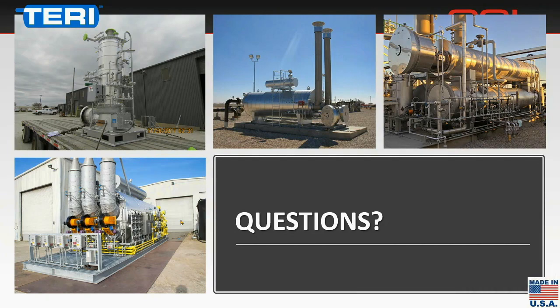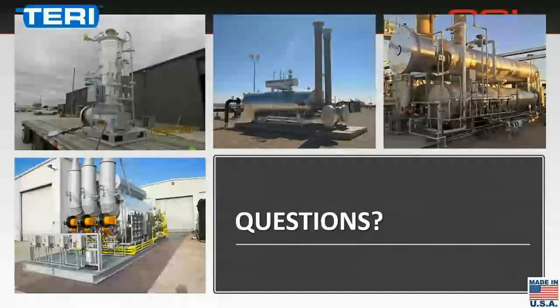Okay, Chester asks, pressure test to establish coil MAOP, testing to 1.3 times MAOP or 1.5 times MAOP. Okay, so test pressure, coil max. Okay, Mike stepped out. I was going to have him field that, but I guess I would say 1.5 times to prove the 1.3 MAOP, but let me write that down.